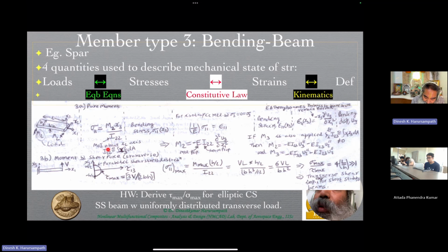And here I'm precisely saying which I it is. It is the moment of inertia about the x2 axis, the second moment of inertia, and therefore it is the integration of x3 squared dA that is coming over here. So once you carry out that simplification, that integral is nothing but your moment of inertia about the x2 axis, so replace it with I22.